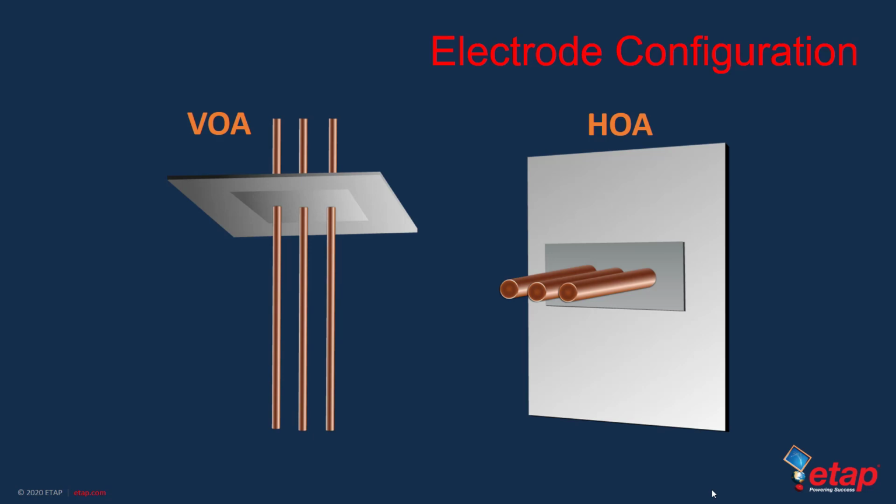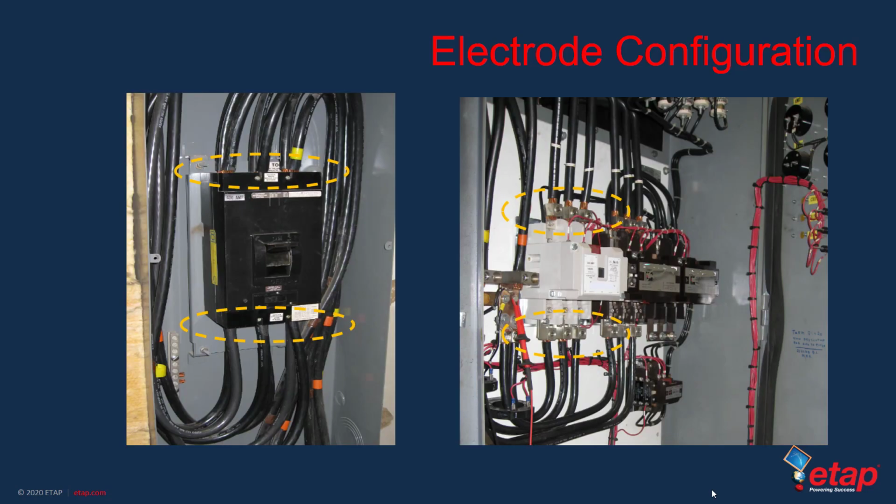We will see in examples later on during our webinar how this can be explained with physical explanation of the equipment construction. These images show potential examples of equipment where multiple electrode configurations are included. The highlighted regions, depending on the direction of the power flow, can either be VCB, vertical conductors in a box, or VCBB, which stands for vertical conductors in a box terminating in an insulating barrier.